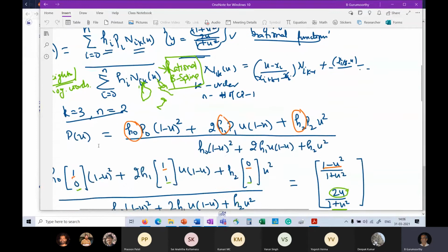And therefore, we define a new curve, though it is not actually new, because the basis functions are still the same. There is only one addition of this weight associated with each control point, and a term on the numerator, which is the weight times the basis functions. But the basis functions are the same as the spline functions, and therefore we call this the rational B-spline, right? We call this form the rational B-spline.